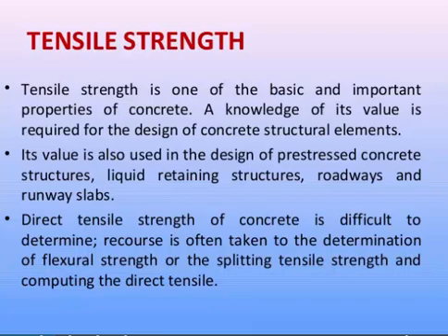Concrete, moreover, is very weak in tension due to its brittle nature, right? So it is not expected to resist direct tension, and concrete develops cracks when tensile forces exceed its tensile strength. Students, why is this test considered an important factor?